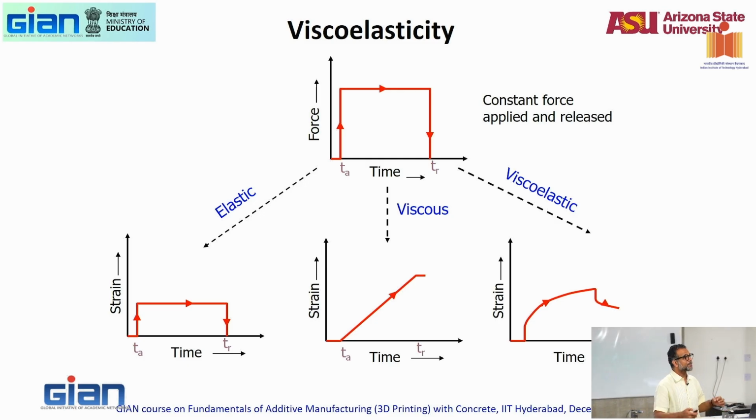If the elastic band is purely elastic, it will do this, right? The function strain. The moment I apply a force, it will have a strain. Whatever I applied, that instantaneous strain, ignore creep. Assume that I have not pulled it long enough for creep to occur. At that time, I have a certain elastic strain. That strain will be constant until I hold the force. Once I take the force back, it will come back to zero deformation. That's a purely elastic material.